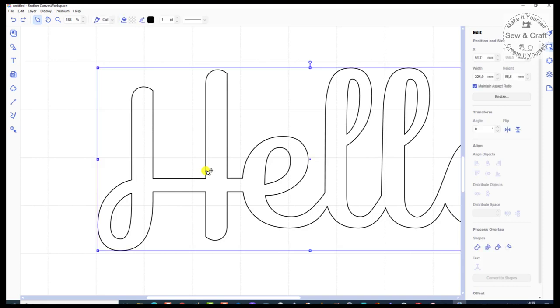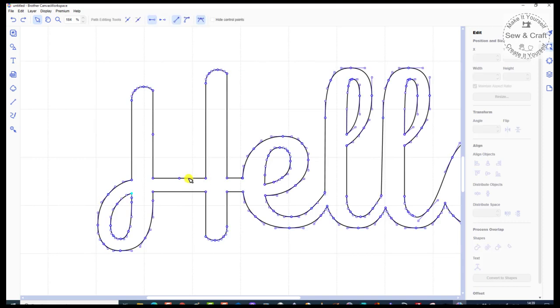And now what I want to do is I want to open that entire line. So this node is going to be in my way. So I could either just delete it by going delete up at the top or delete on my keyboard. Now if I click on that point and say open the outline, it opens the whole line.